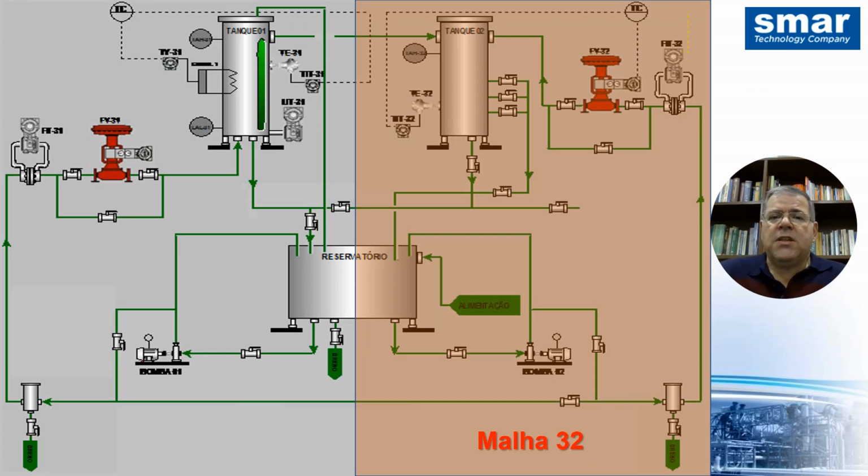On the right side of the plant, we have what we call the mesh of one. Within the mesh of one, let me clarify again, the pump will go through a rotameter. It passes the flow meter. It goes through the valve with bypass and comes to the mixing tank. The water can flow back to the main tank via the consumer valves or through another direct circuit without the consumer valve.